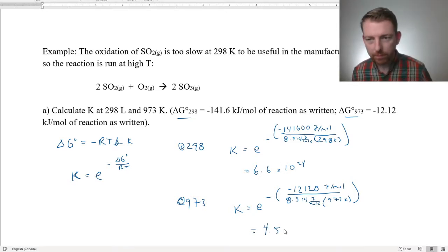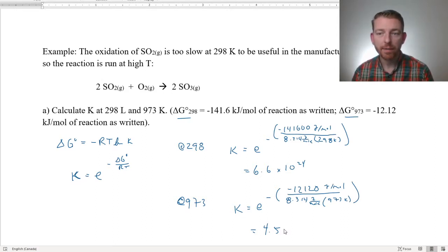So the ratio is a lot smaller. If you were looking at this, you're going to have a significant amount of reactant left in the batch, which may not even be a problem, because as long as you can extract that product, it's going to keep driving towards establishing that ratio of 4.5 SO3 squared per oxygen times the SO2 squared.